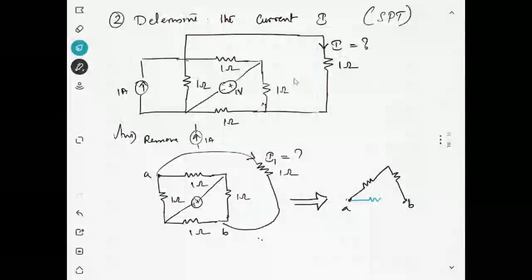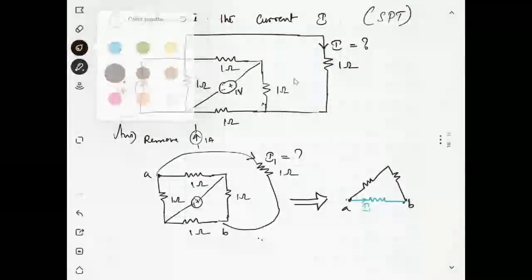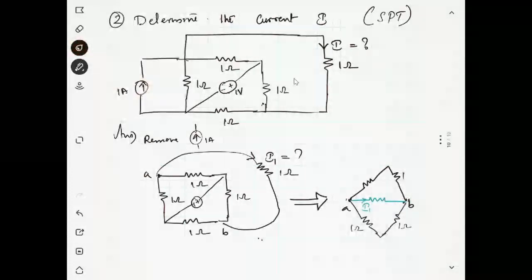I1, and another thing, another resistance. You have 1 ohm, 1 ohm. Is this same or not? Please observe carefully. Is it same or not? Same. Doctor? Now you see here. This resistance is 1 ohm and this is 1 ohm. So 1 ohm into 1 ohm, and if you take these 2, is equal to 1 ohm into 1 ohm. You can see the bridge is balanced.